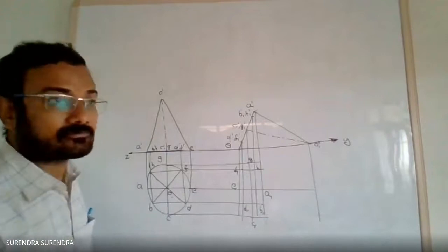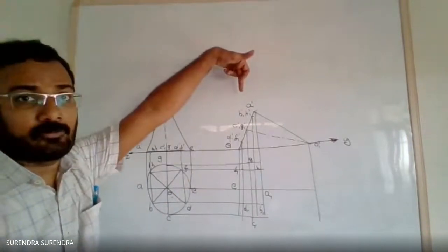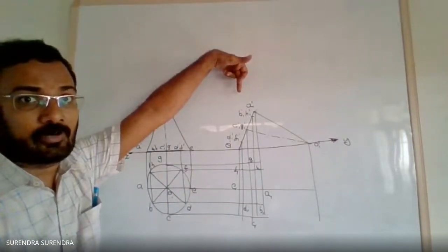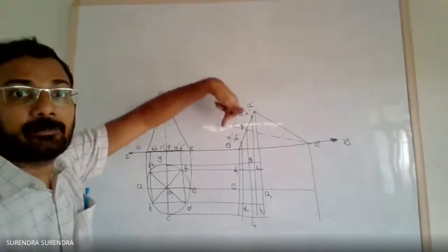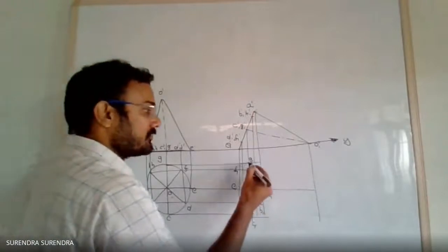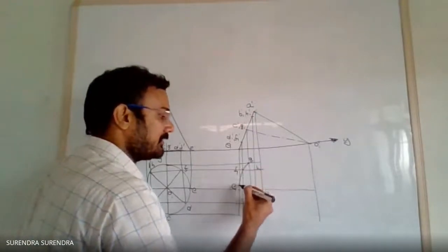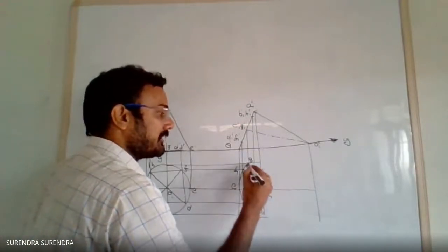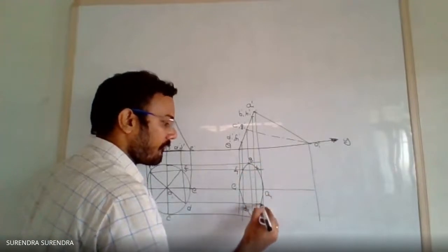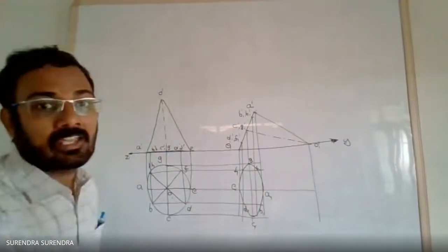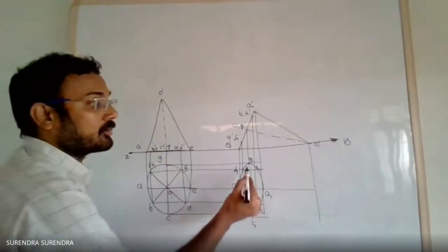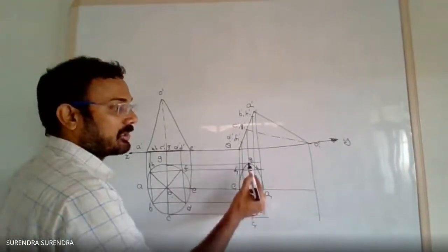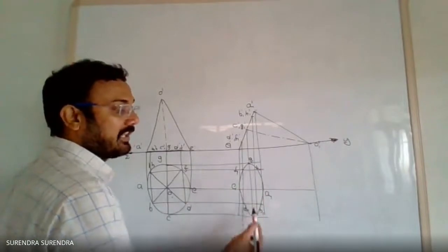H1. Now, if you observe from top, complete base is visible. So join all the base points with a smooth continuous line. You'll get an ellipse. And now join the outermost points. The outermost points are C and H.